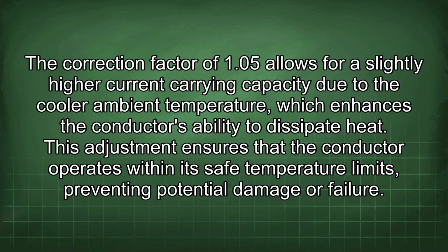The correction factor of 1.5 allows for a slightly higher current carrying capacity due to the cooler ambient temperature, which enhances the conductor's ability to dissipate heat. This adjustment ensures that the conductor operates within its safe temperature limits, preventing potential damage or failure.